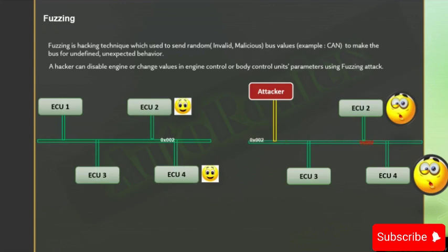So for this, the engine control will be in a particular CAN message. Once after receiving this message with a certain value, the EPS can activate. Certain value in the sense either 0 or more than 700. That is the ideal RPM value.